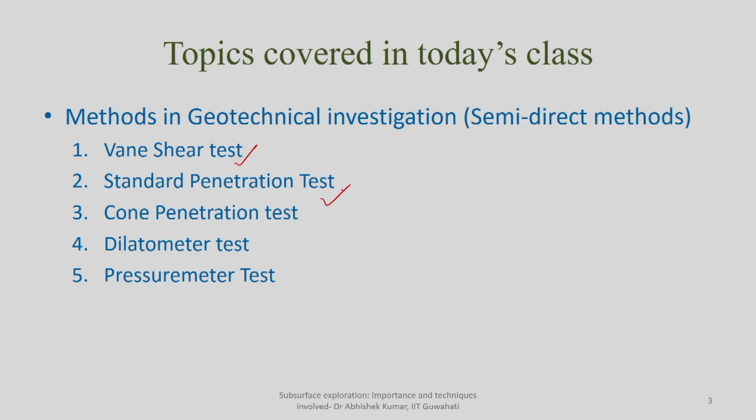Then you have the standard penetration test, many of us know it by the name SPT test. So what are these tests we will be discussing, and then interpretation. Then the third one is the cone penetration test or CPT test, the dilatometer test, and the pressure meter test.